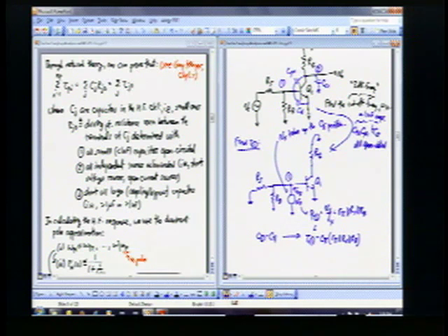Yes? What if the emitter is not tied to ground? Yeah, if the emitter is not tied to ground, that'll be the second example that I do, but just for now, that would be this case, right? And so now you could not just use the shunt resistance for the driving point resistance. You would have to use this equation. Okay? So because it was tied to ground, it made it much easier for us. We did not have to use this equation.